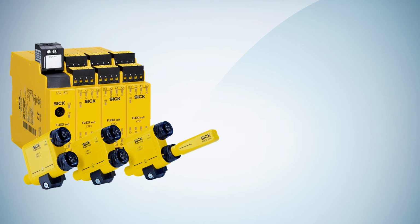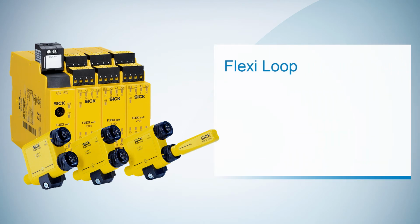Okay, that's the end of the tutorials about the power calculation of Flexi Loop. Summing up, it is very important that you get familiar with the power concept and the use of the power calculator. Then you are able to find the perfect solution for your own power configuration, especially if you have more than one power injector in your cascade.